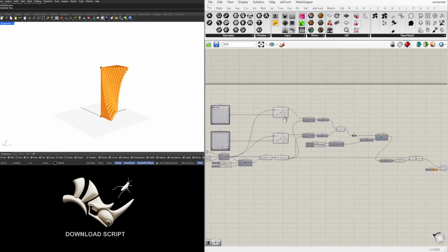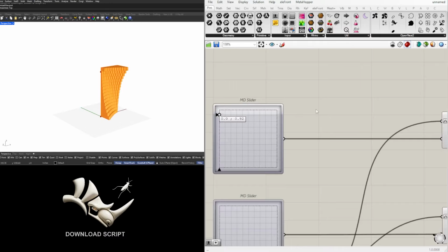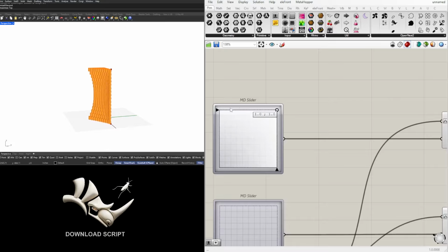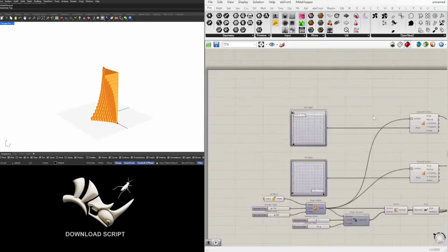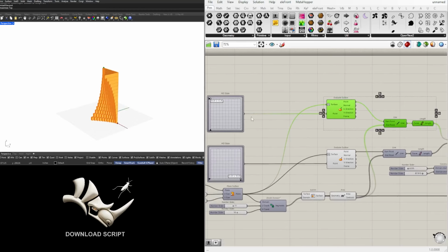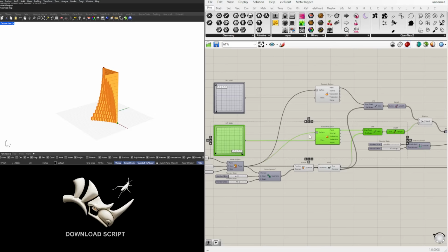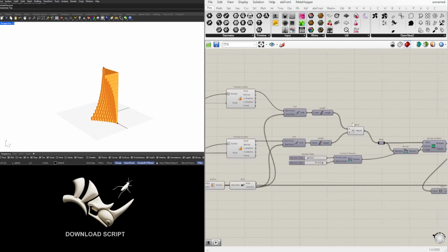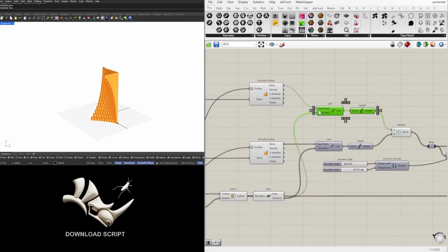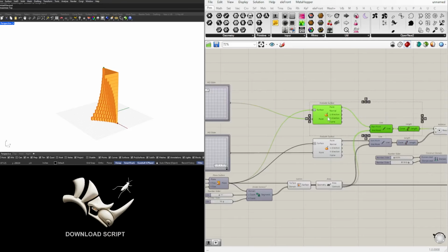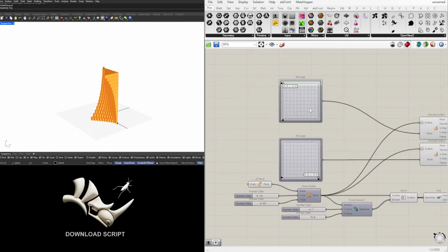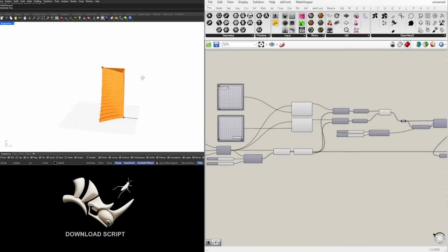So now those are working together and we can see that if we move this one to, let's say, the opposite side, now we're getting 2 different point attractors that we can move around and have the entire design change accordingly. So it's as easy as copying these 3 or 4 components up and then just changing that one and making sure that you add those together. So let's bring this down, bring this down, and now these are going to be the 2 point attractors.